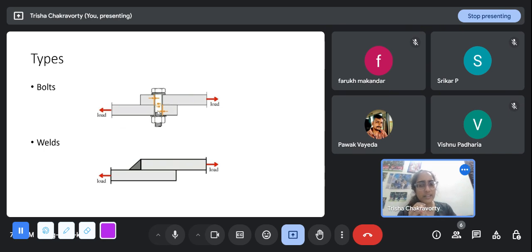First is friction, then when the friction fails, it takes shearing and bearing, and if the bolt material is sheared through, like cleaved through, then the two plates will be wrenched apart and the connection fails. And if the connection fails, the structure may also eventually fail. Generally, the connection is the first thing that fails in a steel structure. So connection design is so important.